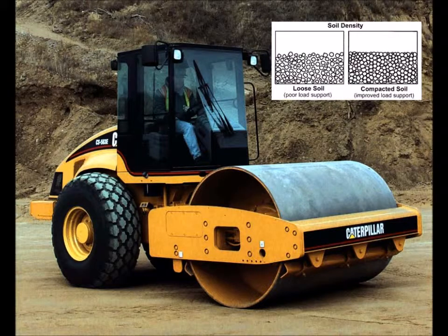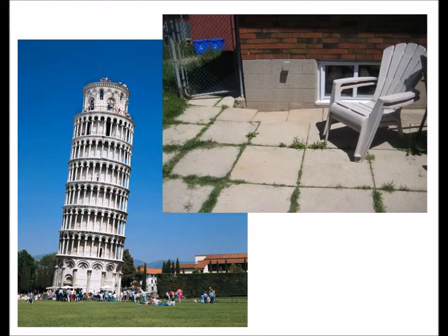This exercise relates to real-world geotechnical problems such as soil compaction and its effects on porosity and soil strength, where due to compaction, the porosity decreases, hence decreasing groundwater flow rate, but the strength of the soil is increased. Furthermore, this exercise observes the effect on sediment due to discharge in different soils.